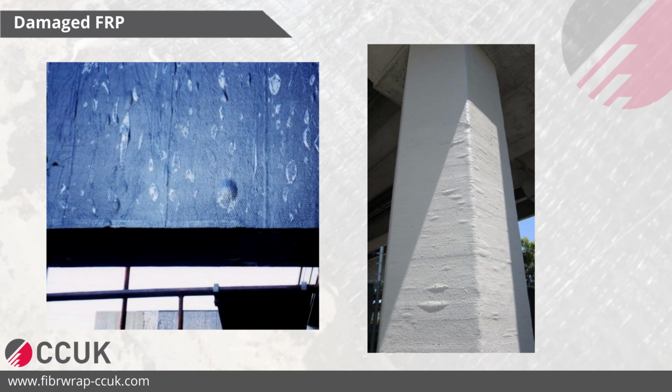may have discoloration of epoxy because of the incorrect climate condition in which it was applied. You can see quite clearly on both of those photographs, and I'd just like to point out these are not our sites. We've had to get the photographs from colleagues abroad, but you can see the air bubbles, or it's not set. So there are air bubbles, there are pockets there. Also, you could see discoloration of epoxy on the left side image.